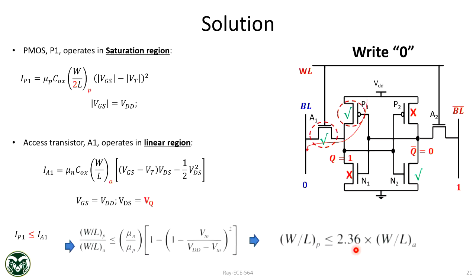This one's overdrive is set, it's just VDS that increases. The more you increase the voltage, the more it can increase. Intuitively I would answer the same: it has to be lower than the strong one, but how much lower are those kinds of details. Doing the specs is hard, and that's a big deal. If you make it 7.4 times, that's a big deal. 1.5 nanoseconds, yes, that makes sense.